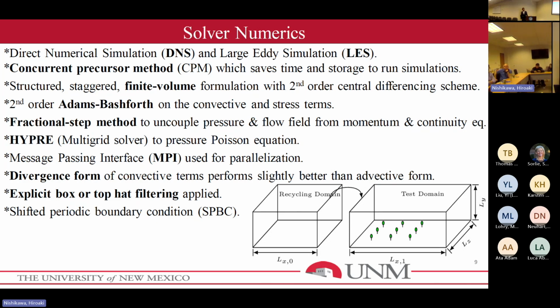Since we actually solve the continuity equation every time step, it justifies itself for every time step. So this is explicit. For the alias filtering we use explicit, but DNS actually has an implicit implementation. And even when you have the fractional step method, how do you still use fractional step for DNS? You implicitly couple several steps. And that implementation took a long time to parallelize.